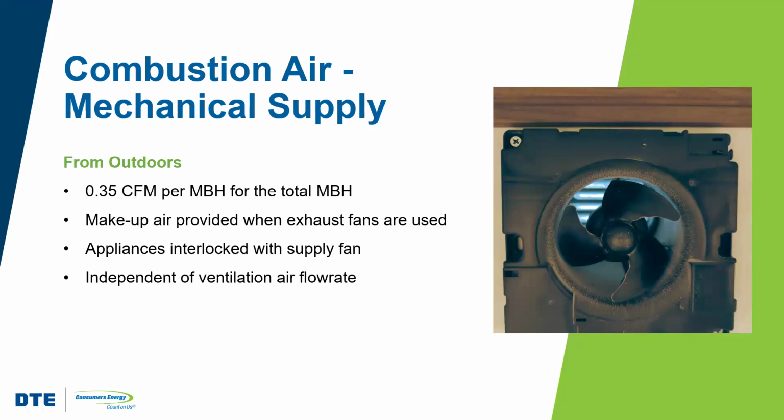You could also bring in that combustion air. You could do that with a fan. So again, we just talked about having just openings and just having natural flow of air. You could do that mechanically as well. So you could have a fan, and then the requirement is that you have 0.35 CFM for every MBH of total capacity in that space.